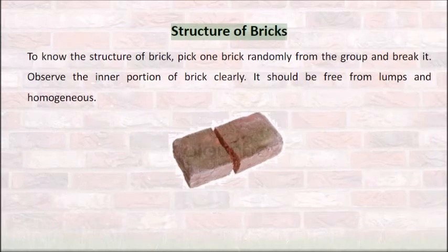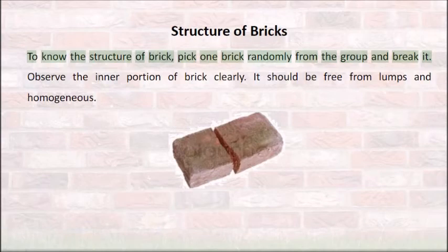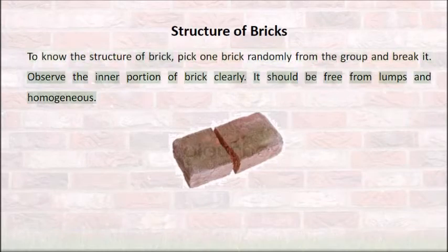Structure of bricks. To know the structure of a brick, pick one brick randomly from the group and break it. Observe the inner portion of the brick clearly. It should be free from lumps and homogeneous.